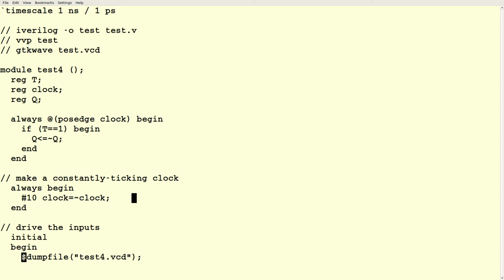Okay, so wires versus registers. Think of a wire as saying I want this variable to be able to connect something to something. It's really just something that can be assigned a value, and that value can be assigned somewhere else or used in an if statement or something. A reg is something that you want to have actually remember a value.